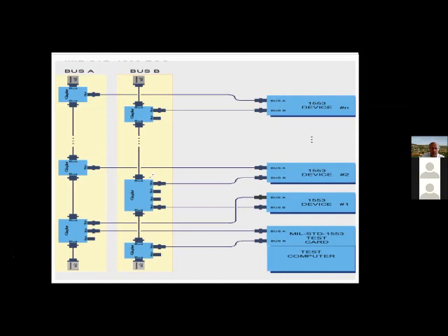Here I've got the 2 of these RTs are both on bus B on the same coupler, but on bus A they're on different couplers. These are things that don't matter. They probably won't happen. I would guess that most designers are going to say bus A and bus B should be exactly parallel. But according to the spec, there's nothing that requires that. So if it's convenient, you don't have to.